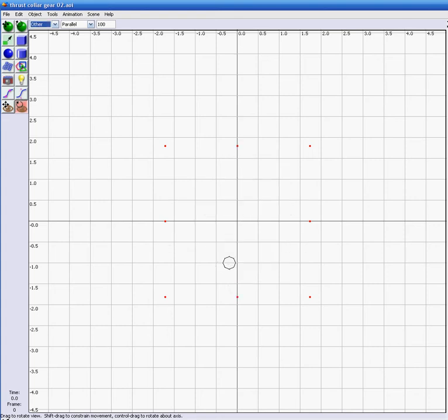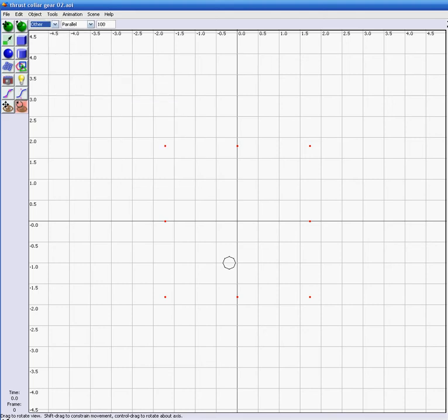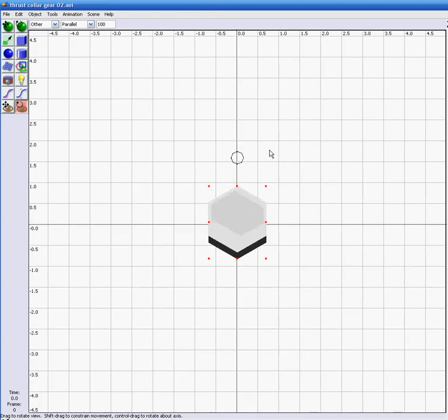Then you want to develop an outline for the nut. There's another script that you can get that allows you to develop polygons, and we won't go through that one because it's just not all that important right now. So let's go get our polygon. Let's show it. Okay, now that is the size of a hexagonal nut that will screw onto a 3/8 inch threaded rod. Now let's go ahead and extrude that one, and we will get a hexagonal rod. Now the question is, why do we want to do that? There it is. You see, nothing to it.